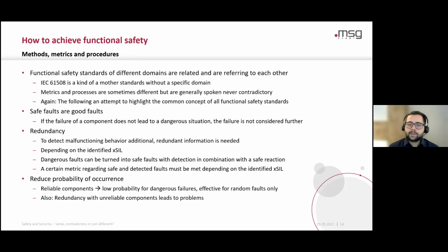Yes, the question was, what is the safety design approach when stopping a car or a train? For example, in a tunnel, that might be a huge risk, for example if the train is on fire or the train control system is harmed by fire. This is a good question. For trains, it is not allowed to stop in tunnels, and on each track there might be additional places where you must not stop. This is considered, for example, when you pull an emergency brake in a tunnel, then the train will try to reach the next station. Don't try this, but when you pull the emergency brake in the Vienna Underground, the train will reach the next station before it stops. It just inhibits that the train proceeds the journey to the next station after that station.